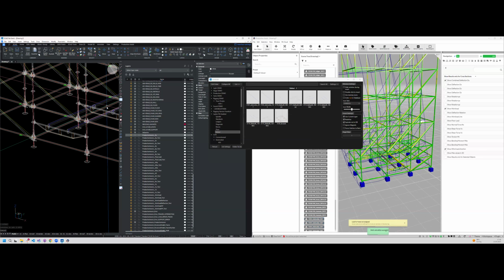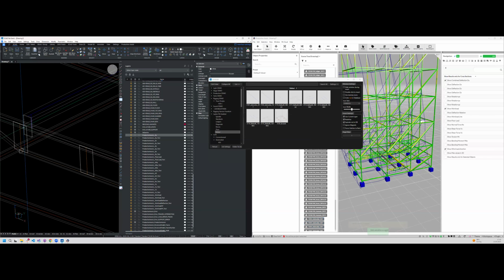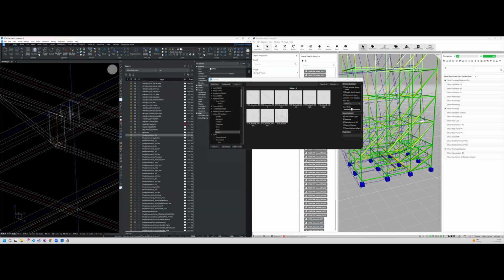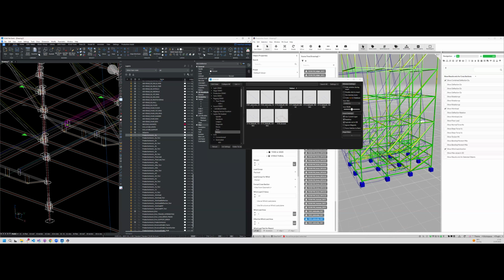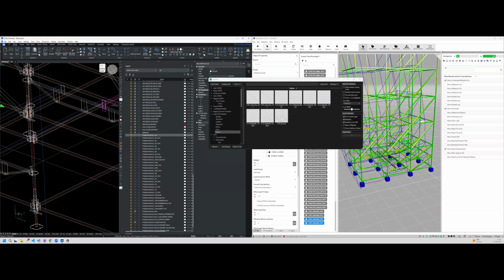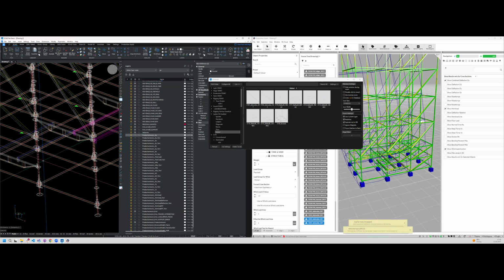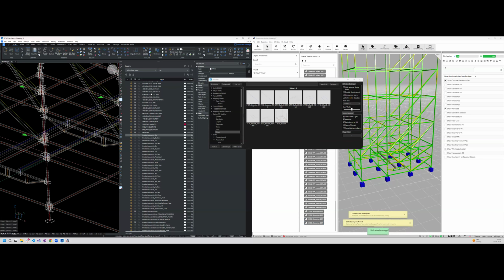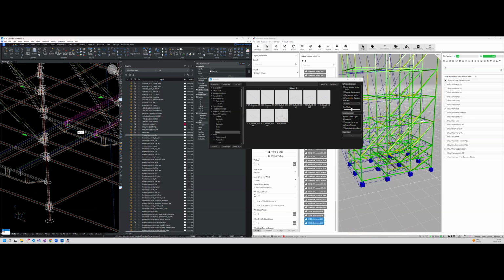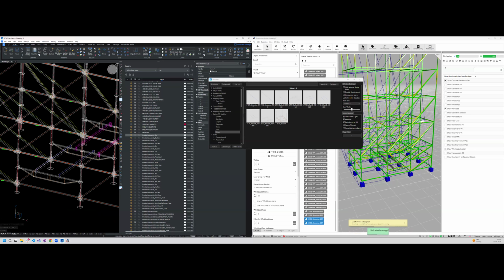You will see that it doesn't work like this because there is a collision. So we will select them. I do MX for move in X direction, and I want to move it. Now it has moved farther than I wanted, so let me undo this so that it's back like this. I only want to move it in X by about 20 centimeters, and then it's a little bit intersected with this, so that I can do this.